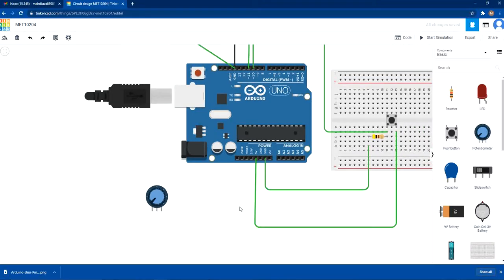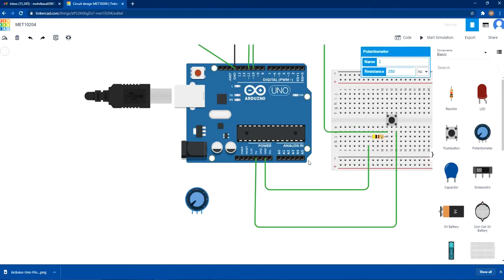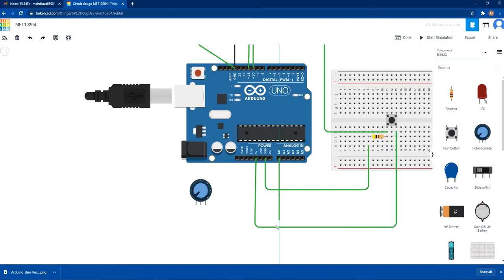So for this particular condition, since previously I mentioned the analog pin, we need to use a special dedicated pin from the schematic. In this case, we use either pin A0 to A5. So let's say we select pin A0 to read the voltage from the potentiometer. So we just make the connection from A0 to the center of the potentiometer.